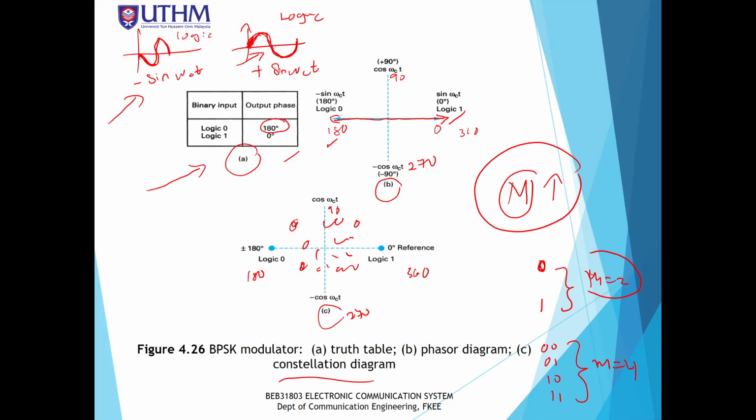So that's why in the constellation diagram, we want to see the distance in terms of phase. In practical cases, we want to go to higher modulation techniques, but we also need to be careful with the symbols, because when we go to higher modulation techniques, we have many symbols. That means the constellation points will be close to one another, and it is more prone towards error.